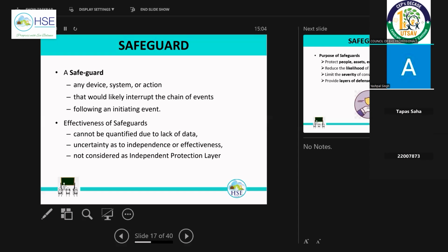Similarly, a pressure alarm may also be there. There will be a control loop also. So high temperature will close the steam supply valve if there is an XV or control valve. Again, if there is high pressure, there may be a PSV. The PSV will release and reduce the pressure and eliminate the damage to the equipment.